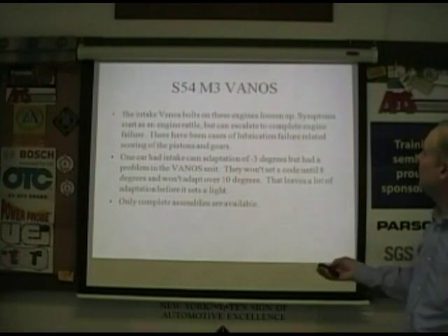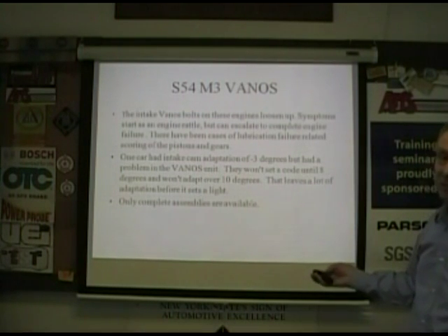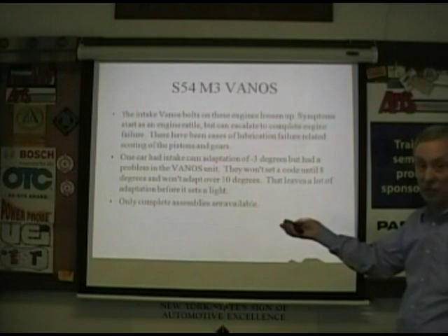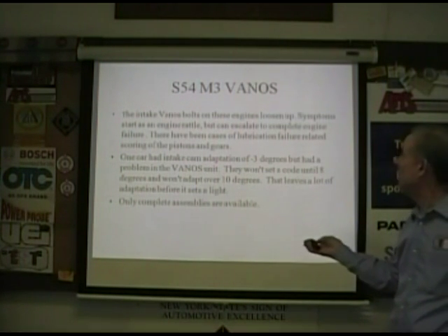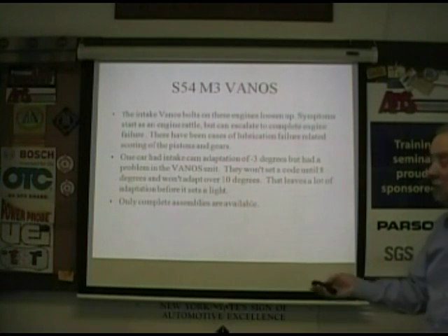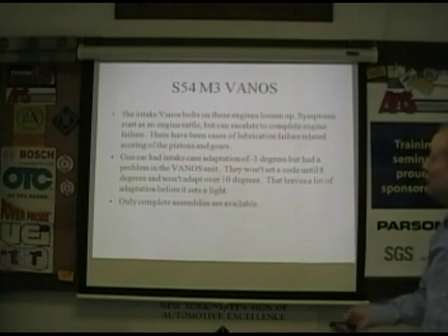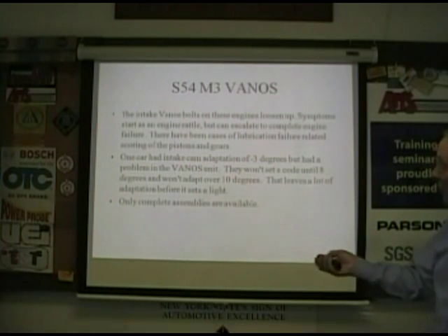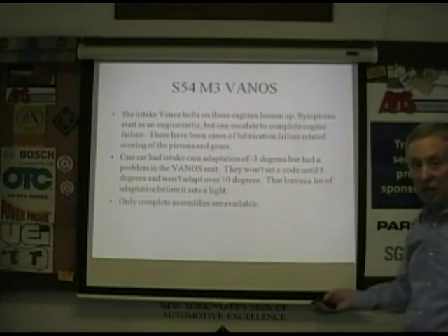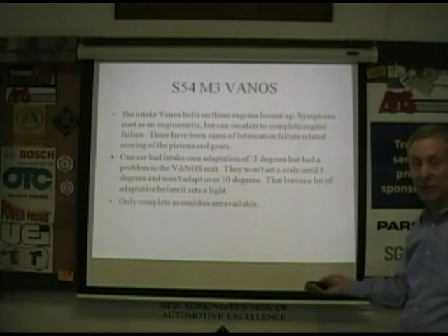The thing to understand here is, again, it's got special oil, 10W60. You can get some engine rattling, you can get noises in this particular one. And it can escalate to complete engine failure, especially considering how these cars are driven. Really it's recommended you have to use the right oil. You also have to be careful about when you draw the line on the Vanos. Vanos does not have serviceable parts. You have to change the whole thing. It's very expensive. It's over $2,000.